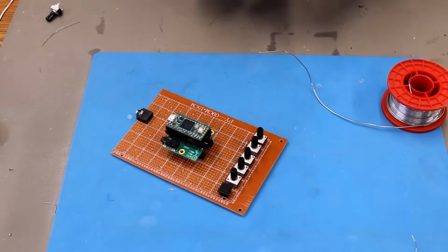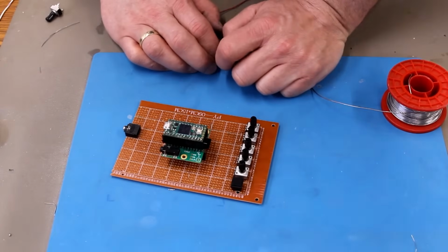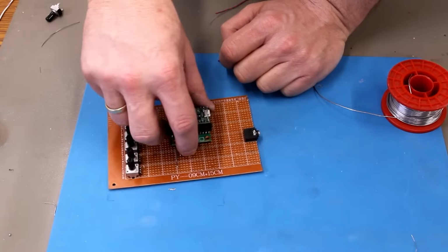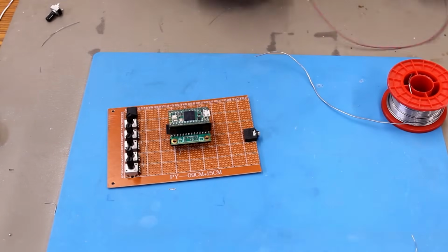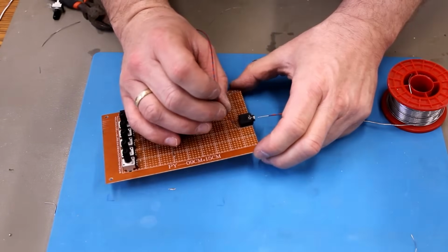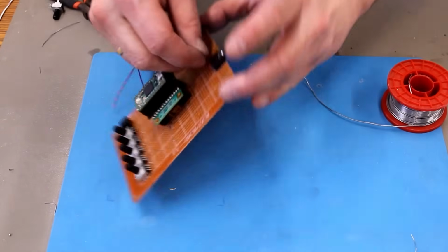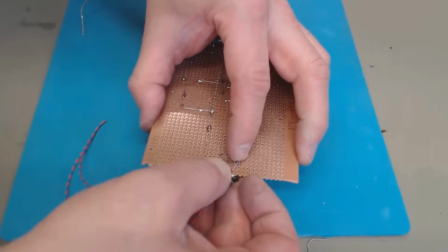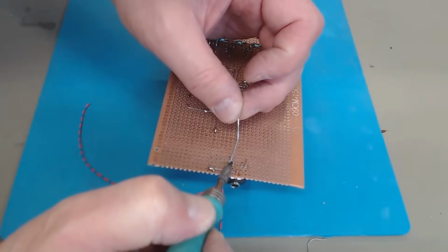And the ground is already connected, so I only need to hook up the 2 pins that are closest to the Teensy, and then use those for audio. I'm going to solder them directly onto the board. First one goes in there, second one goes in there, flip it over. Yeah, that's going to be it for now. And like I said, it's a prototyping board, so it's fine.